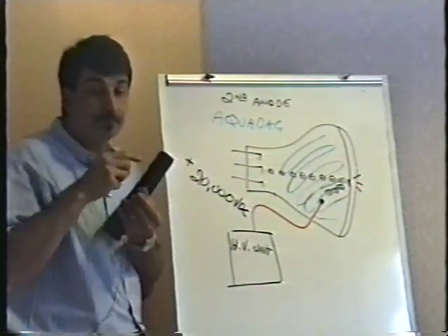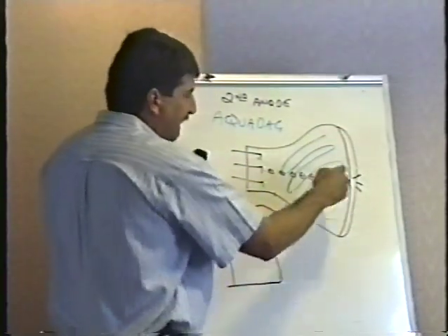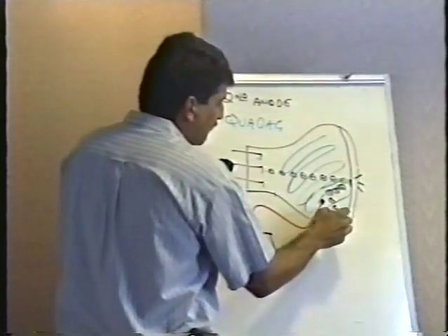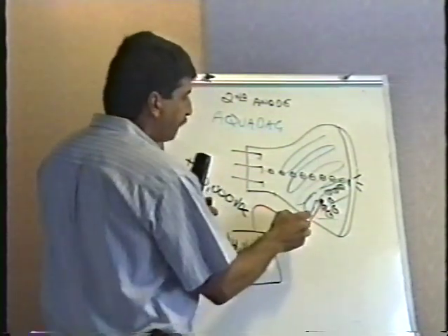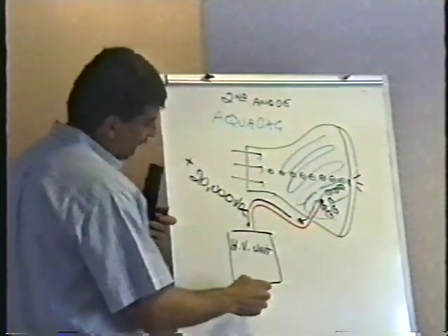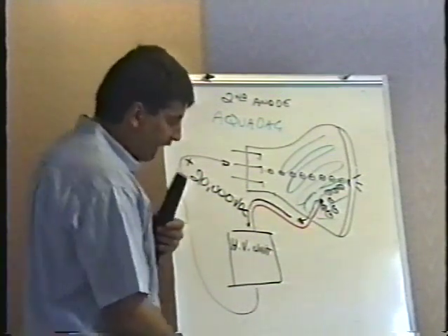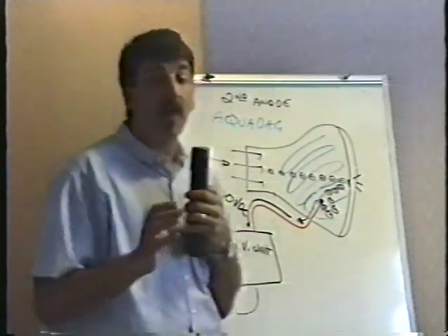Same thing. Well, here's what happens. After the electron bounces off, it attaches itself to the nearest outside wall, charged at plus 20,000 volts, where it gets sucked along the wall and out the high voltage wire and into the high voltage unit. Presumably, eventually, it gets pumped back up somehow and shot back out at a later date. I'm not really sure how that happens, and I don't really care. But that's what the high voltage is for. The high voltage is there in a monitor to remove those spent electrons after they've struck the front of the screen.